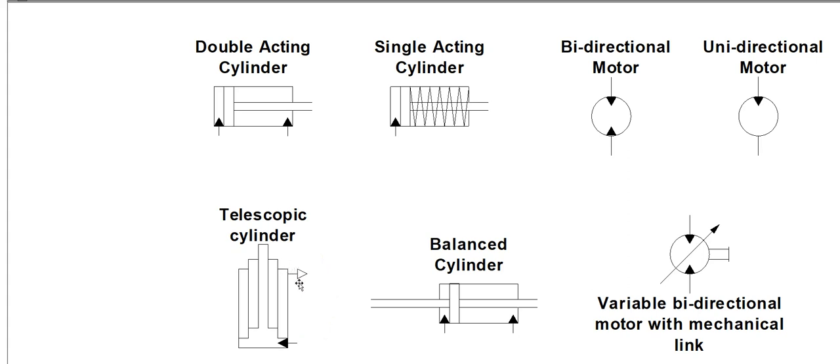Hollow arrows are going to indicate gas. So in this case, air. That is a vent. So that's just showing a little vent line on the top, showing that air can go in and out of that chamber so it doesn't ever airlock or hydrolock inside there. So you'll see that a lot with pneumatic schematics as well. If you ever work a lot with pneumatic systems, on those schematics, their symbols look almost identical to hydraulic, but you'll notice all their arrows are hollow inside.